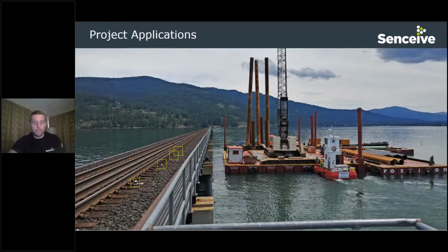So this is a case where it's a long rail bridge. As you can see, a new bridge is being built very close to it. So in order to monitor that they didn't do any damage to the existing bridge, they installed a whole bunch of our triaxial tilt sensors along the bridge itself. You can see them here highlighted, right on the sleeper or the ties. And again, those are all talking to one another and then all communicating back to a gateway so they can check the data in real time.